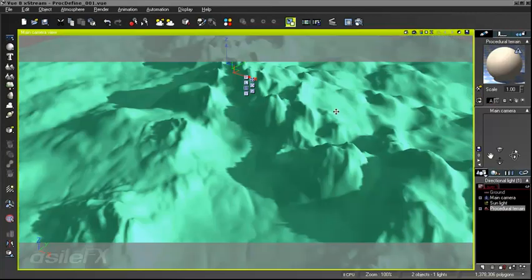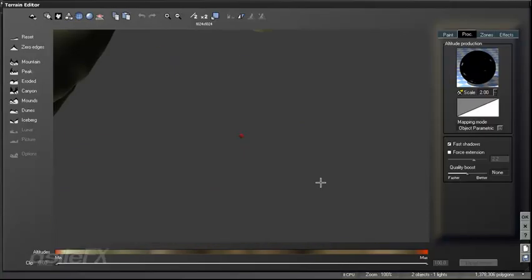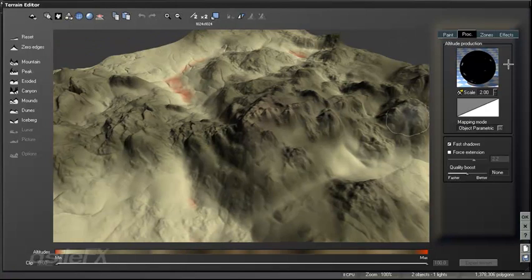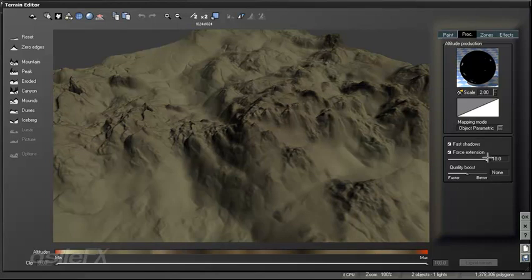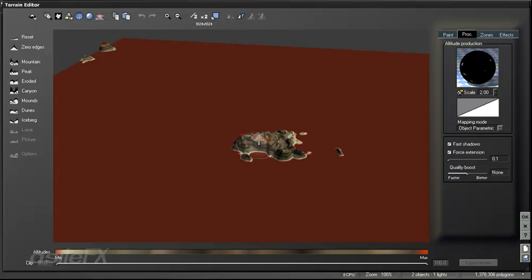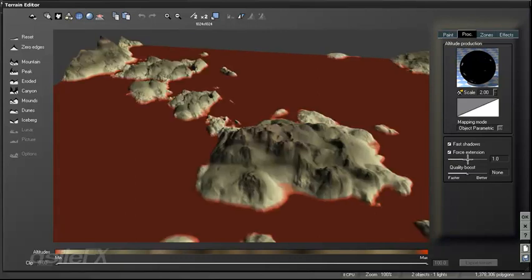So I am going to continue this process and show you some other techniques along with it. One thing you can do that's pretty neat is if we use the force extension, we can modify the terrain outside of the defined value. So I'm going to force the extension, or actually reduce it, to 0.1. So now we just have this very limited region. Might need to get a little more data from it so we can increase that amount.